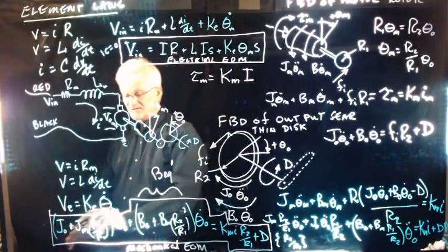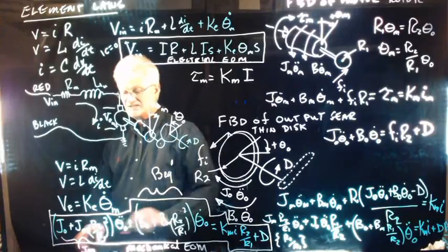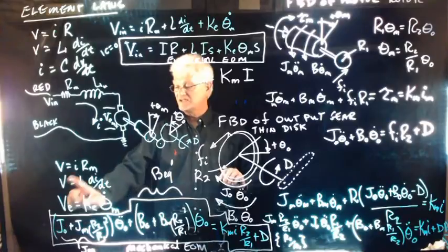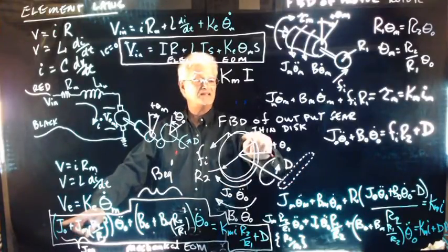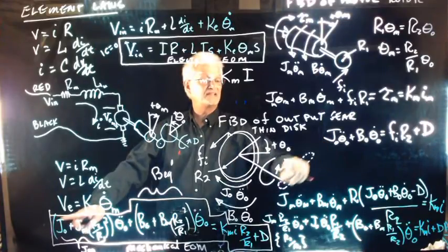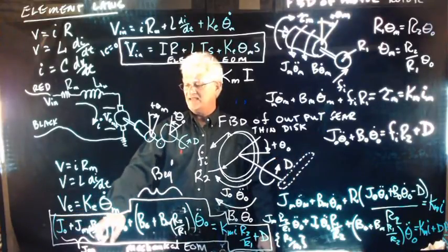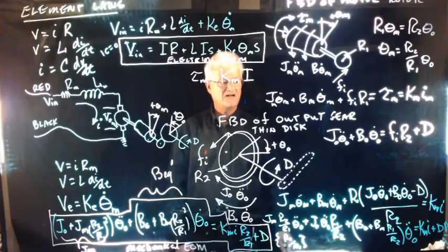Again, I'm going to call this J equivalent. So the equivalent rotational inertia is the rotational inertia of the output. That might just be this thin disc, but we might have something else on here, a robot leg or the wind turbine blades that you see out across the plains. And then part of the inertia is whatever's at the motor, and that's multiplied by the gear ratio squared. So I've got all those things.